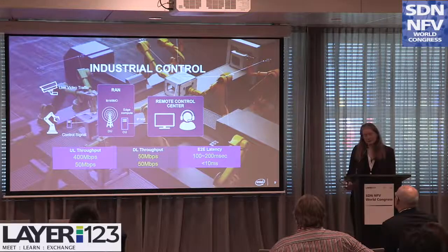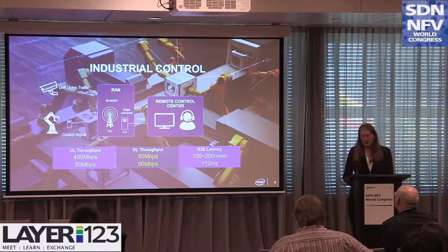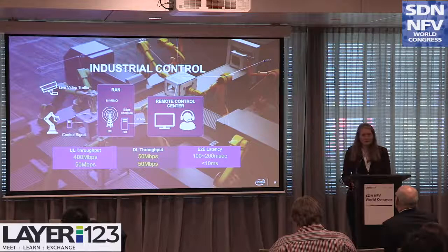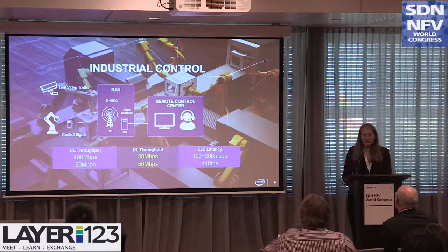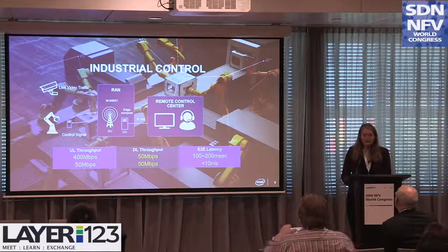It actually turns out from a physical layer perspective that it's the ultra reliability that's the hard part to do. So again, there are particular algorithms we can select in our receive chain that improve that reliability, or we can use a technique called transmit diversity, where this device's signals are received by multiple cells, and those signals are then routed back to be processed in one location within the factory. And that turns out to greatly improve the reliability that we get.